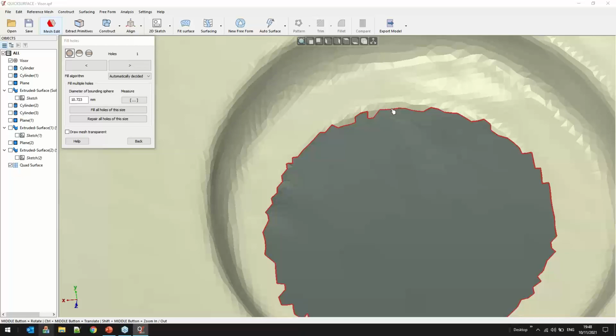And now I will go again to the split mesh. If you remember, I showed you how you can split the actual mesh, but what we have here is two solids, I mean a solid mesh and a solid surface like this one. I just need to select this so it knows that it will work with the cylinder. You can actually apply the other operation, which is called cut. The software will apply a Boolean operation between the cylinder and the mesh, and create a surface that is suitable for printing.